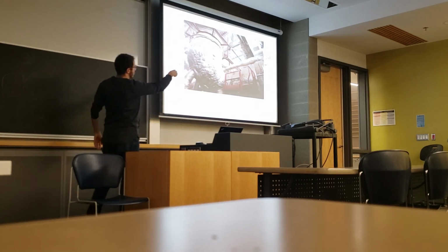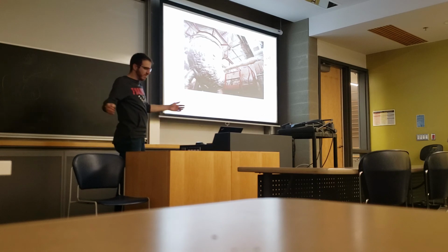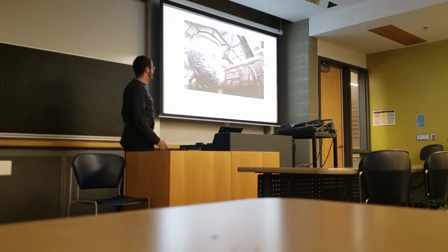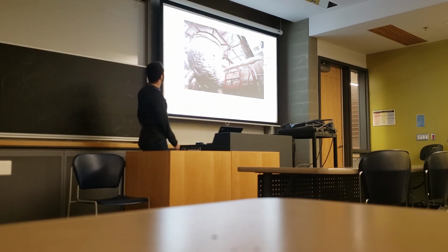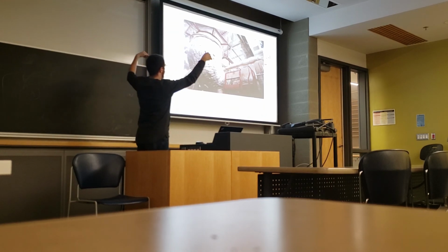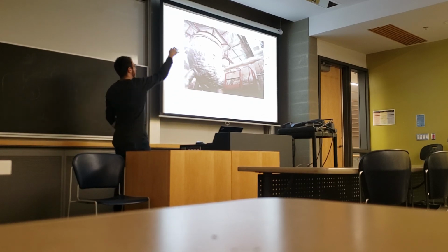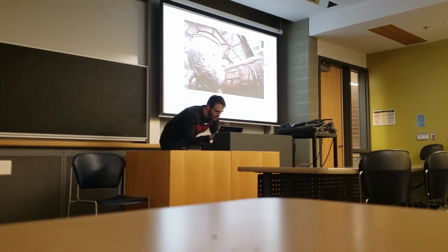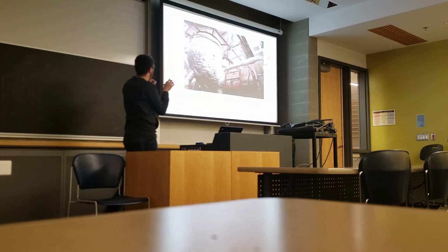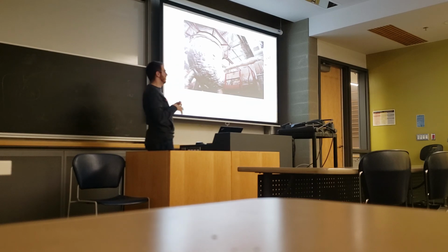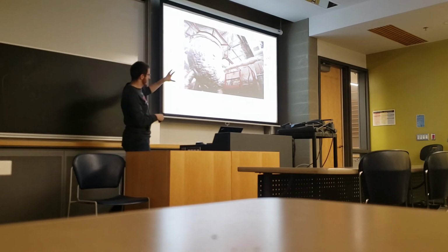You have the compression section, almost 5 or 6 meters, and also the turbine of about the same size, a bit more, and the combustion chamber from two sides. This is just one side; from the other side we have another one. These sprays you see here are igniters, which make ignition and spray the fuel into the combustion chamber.